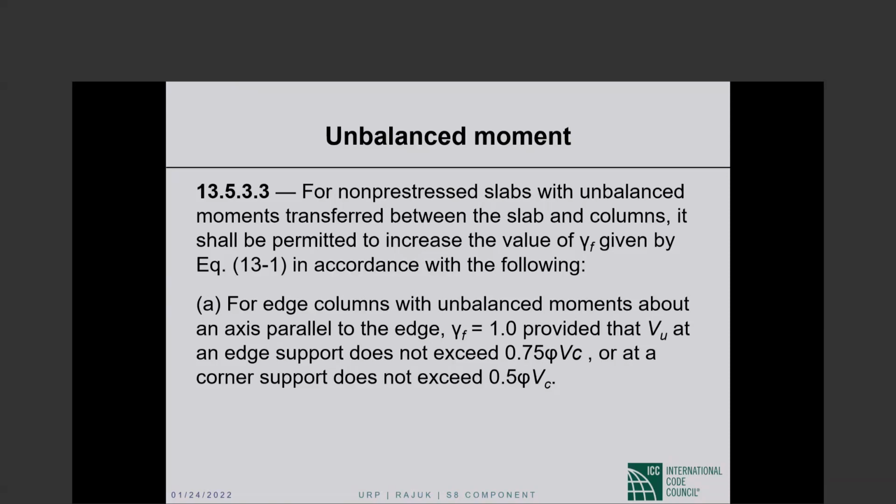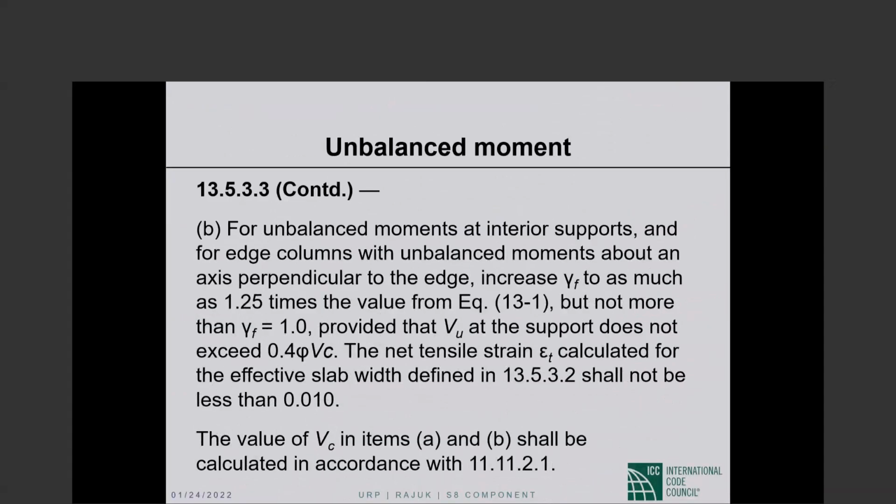That's the way to look at it. It's not that we are increasing the portion of the unbalanced moment carried by flexure. We are decreasing the portion of the unbalanced moment that is carried by shear, thereby relieving the punching shear problem that we always have. So this is great flexibility if you understand how to use it.